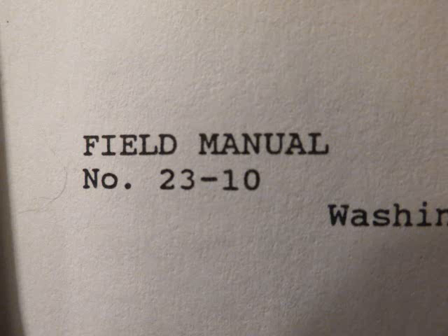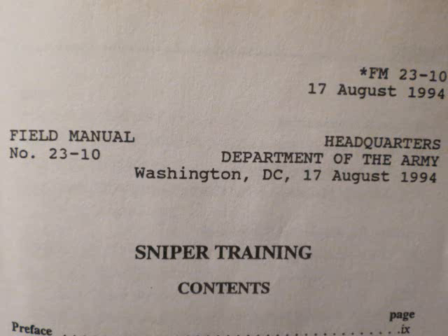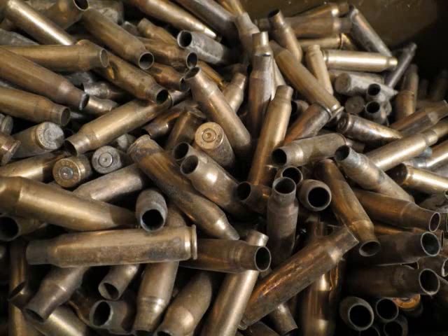So if you read any of your gun maintenance manuals, like your field manuals, or if you're in field artillery and you're reading the 640 manual or any of these where it talks about your propellant residue problems, they're going to talk about how increased propellant residue is going to accelerate bore wear by basically chemical erosion. It's going to cause corrosion, and it's going to augment the abrasive action of the projectile. So it's kind of like a little sandpaper residue going on inside there. So it can accelerate bore wear.